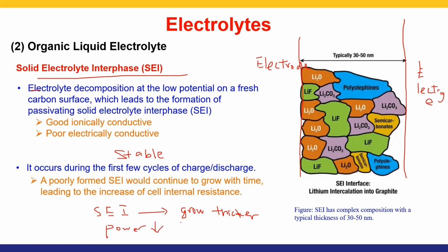One of the reasons that the battery degrades over time is that when we charge and discharge the battery, the lithium ion will intercalate and deintercalate from the SEI, and eventually the contraction and expansion of the SEI will cause the layer to crack and a new SEI layer will form.